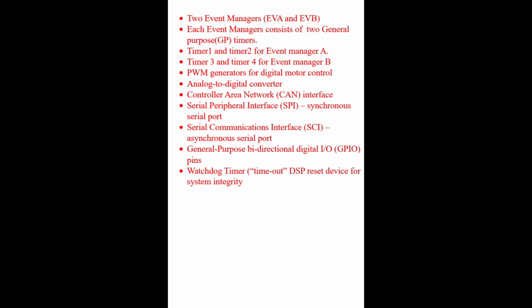If you have multiple processors, there will be one master processor and a few slave processors. While communicating between the master and slave processors, we need a proper network to communicate without malfunction, because sometimes a slave processor will give a signal opposite to the master processor, and the device will not obey the master processor if you don't have a CAN network.